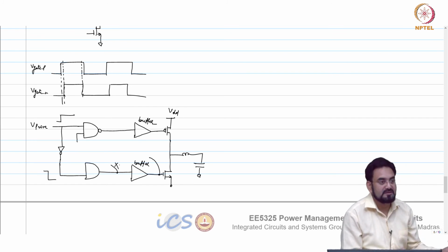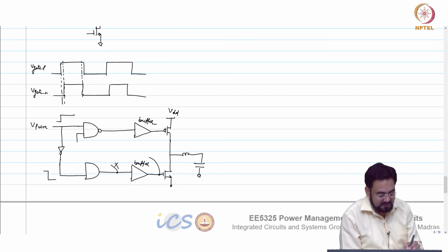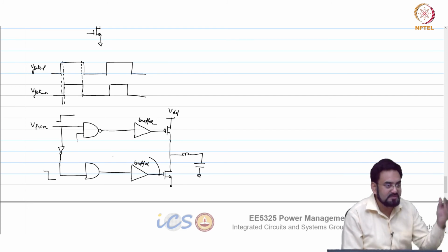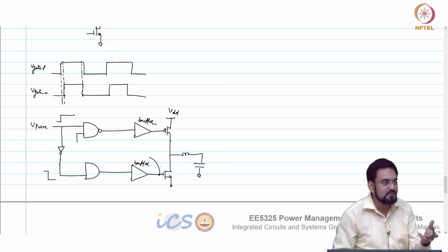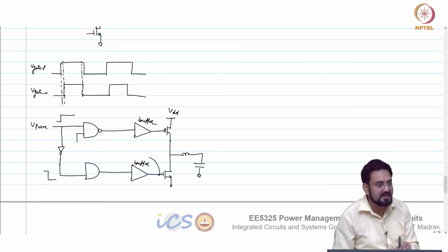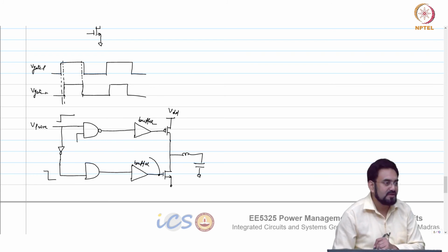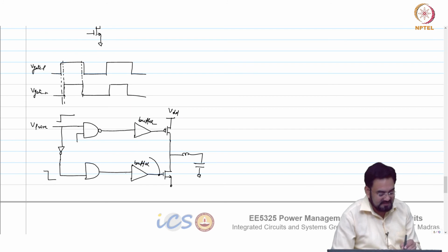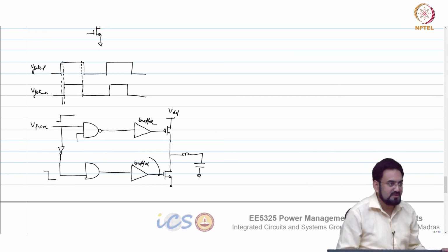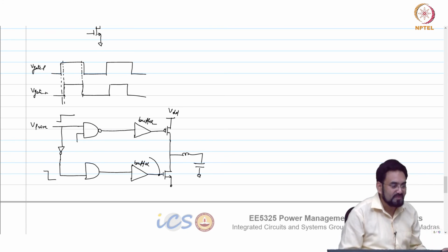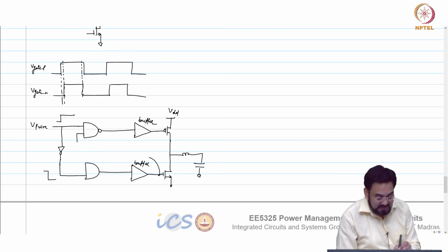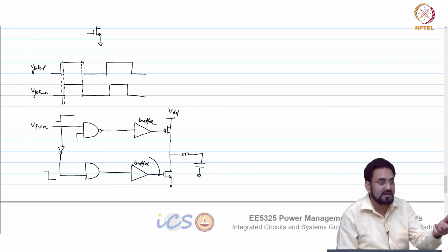This is wrong, but if you look at any digital logic book or anything, they might be taking feedback from anywhere, because they are not driving such a huge gate. So the rise and fall time and delays looking at this gate node will be relatively the same compared to the previous stages. In that case, you can take the feedback before this buffer also, but here you know that the rise time and fall time itself is 1 nanosecond.